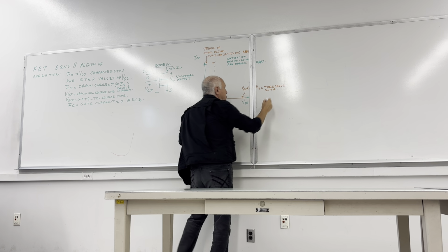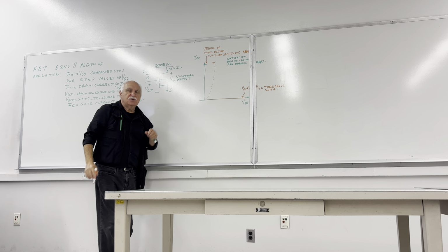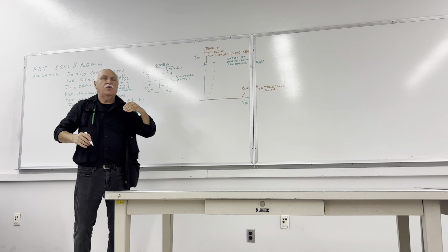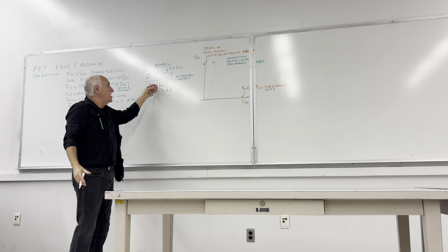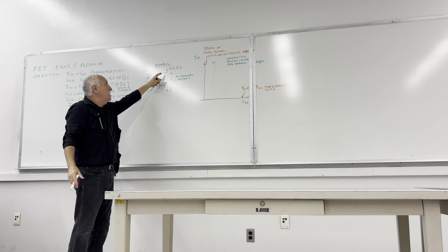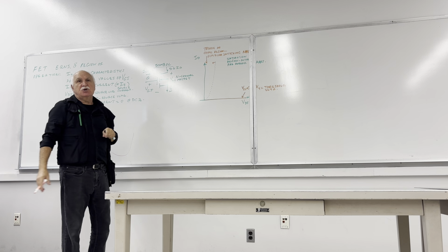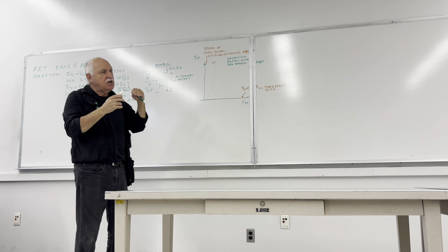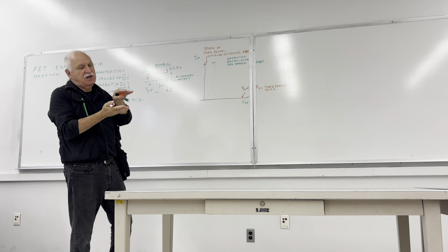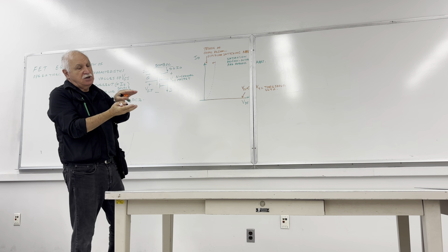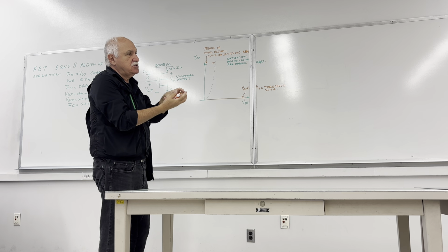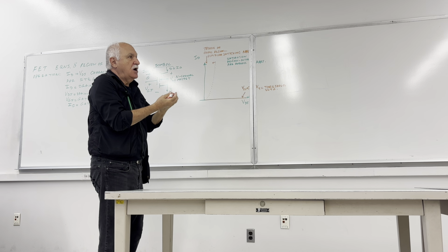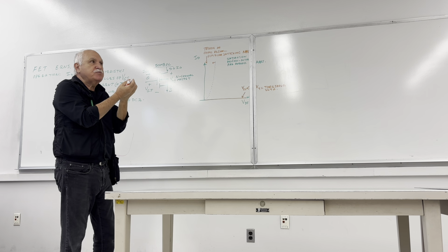Threshold voltage is usually the voltage necessary for inversion in order to create mobile charge between the drain and the source channel. Once the gate voltage exceeds it, there is enough electric field between the insulated gate and the substrate that electrons come underneath the plate.